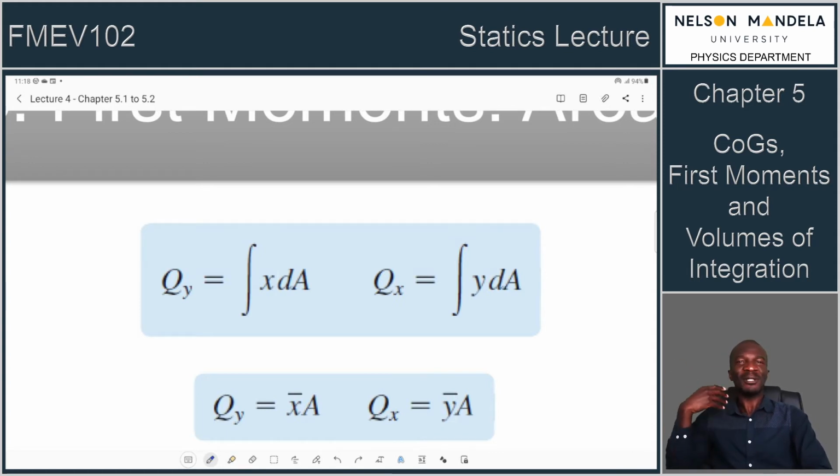Moments are conceptually the same, right? The moment that you're calculating with the forces is the same moment that you're calculating with the areas. The only difference is that you found a way of mathematically eliminating certain parts of the equation until all that remains are areas. So if we have areas only, a first moment is the moment of an area, if you would like to summarize it that way. A moment that we learned earlier was the moment of a force. A first moment, you're just looking at it as the moment of an area.